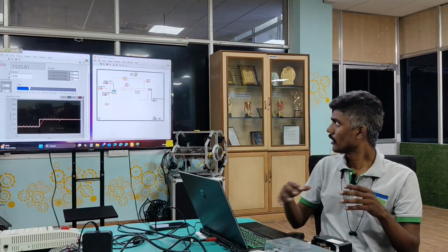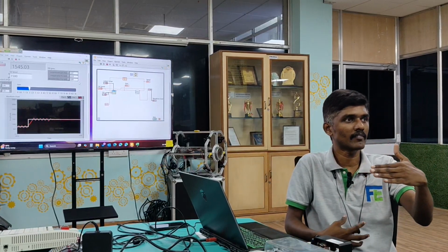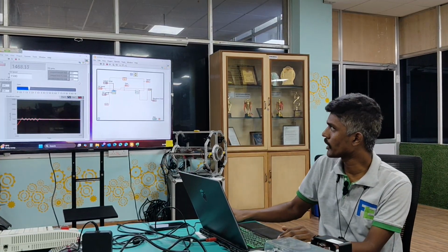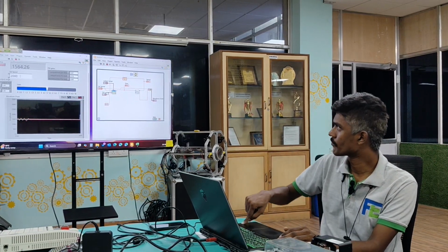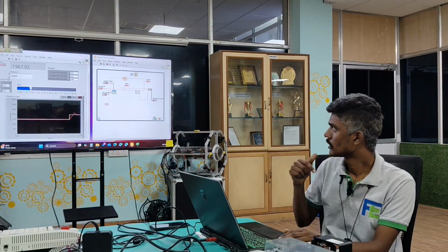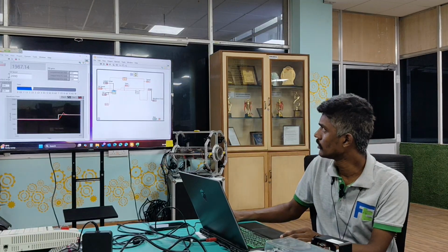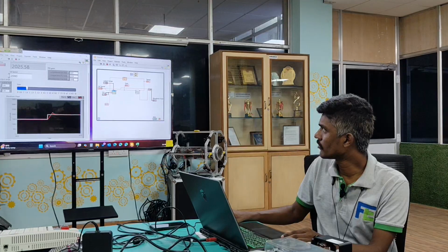Okay. Then you have two options. Once you start to get the peak overshoot for your integral gain value, either slightly increase your integral gain value and achieve your set point. Now I am achieving 1500, I am increasing to 2000. Started to tune the value. If you want to reduce the damped oscillation, then slowly increase your derivative gain values.